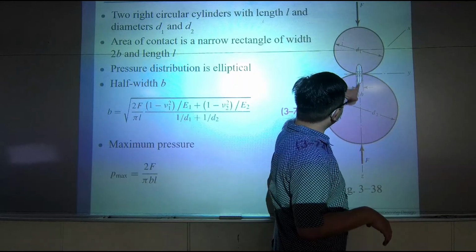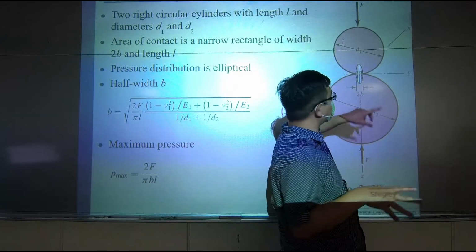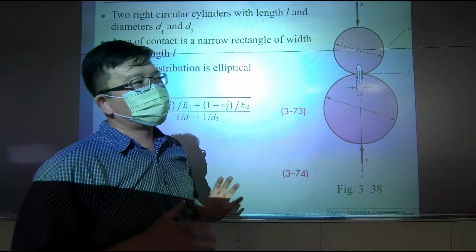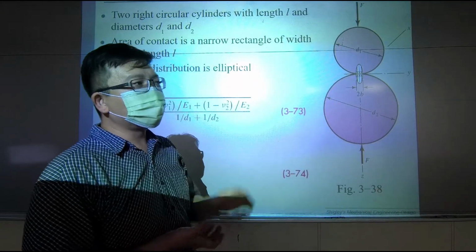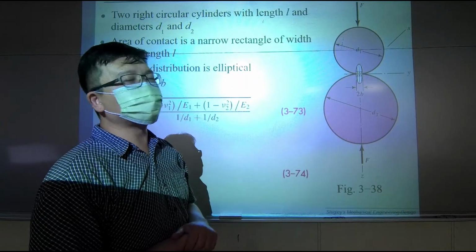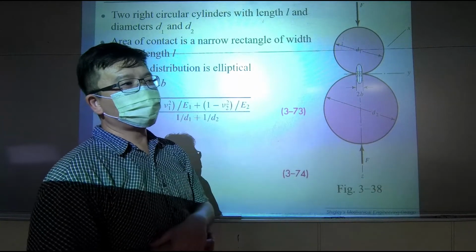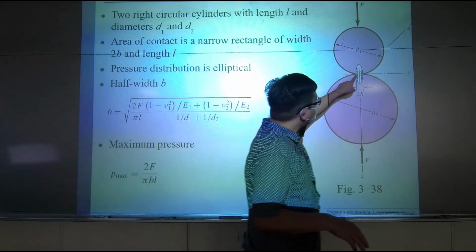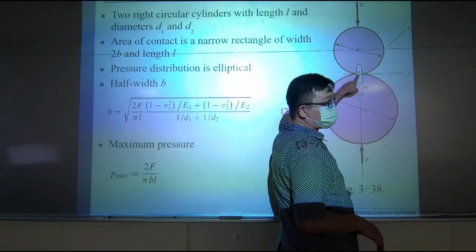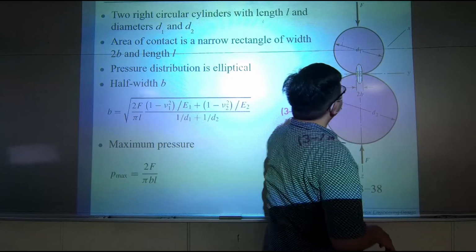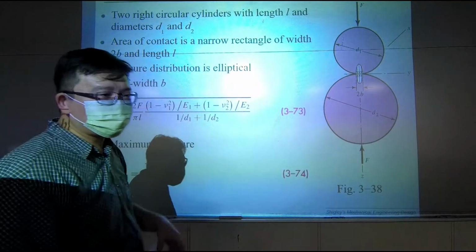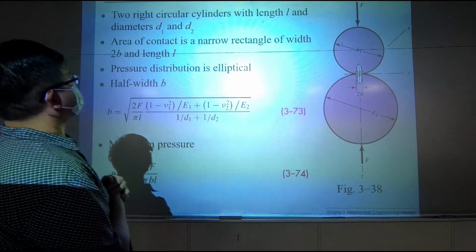This drawing indicates how much stress is concentrated at this area. This kind of contact stress is not considered in previous analysis. For bending, we don't care about this local concentration of stress. But this is important for conjugating mechanical components.